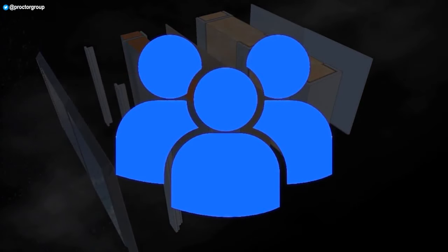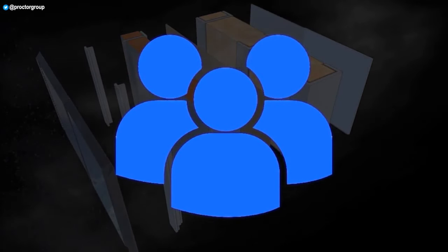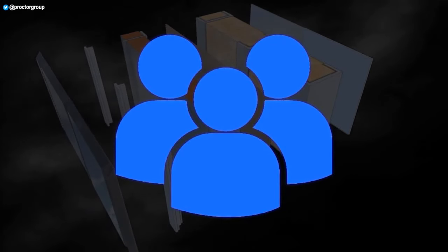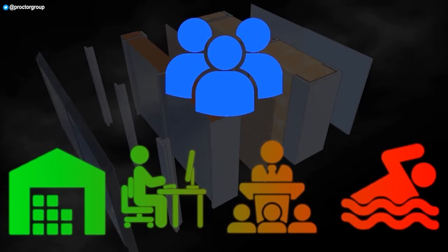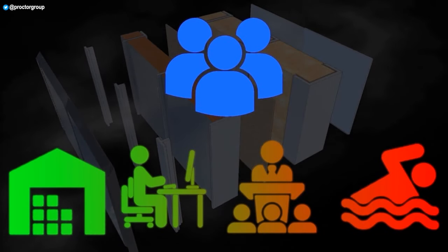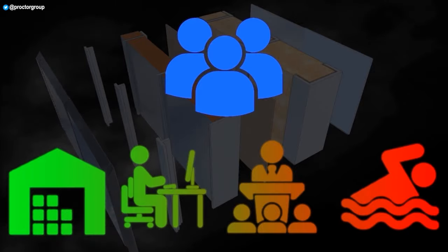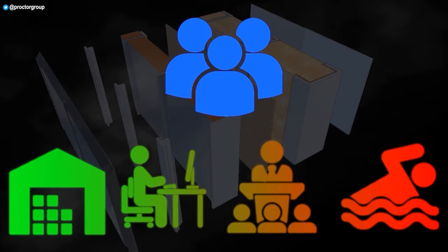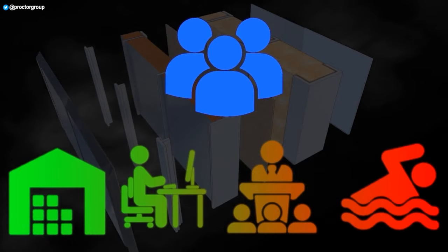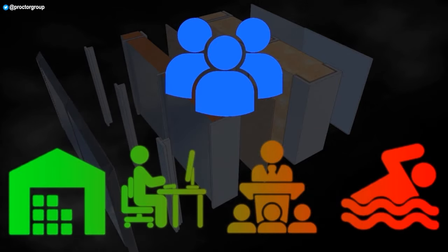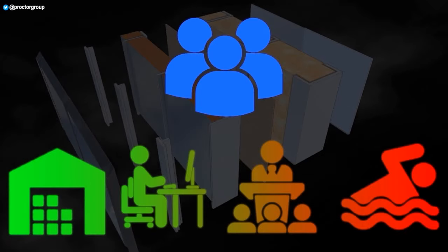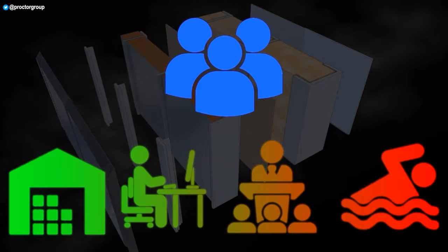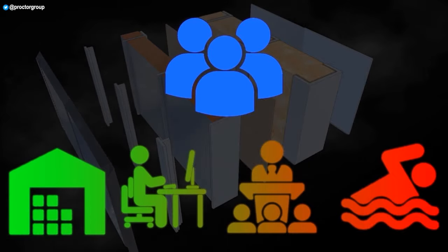Internal moisture sources must also be considered. Achieving an effective and efficient moisture strategy depends on the design being carefully matched to the building's function. The same office design that works for an office may not work well in a sports centre, for example, at least not without significant over-engineering and added costs. Developing a thorough understanding of both how the building as a whole and specific areas within the building will be utilised by its occupants and the corresponding moisture production is key to achieving a robust and cost-effective design.